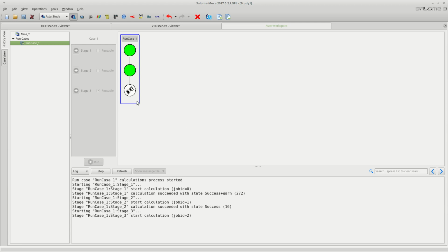Now this third stage will take a significant amount of time. The reason being, it has to save all the time steps, and the output file is also going to be bigger than what we had seen earlier. So that's why in dynamic analysis, getting the whole output is not recommended, especially when we go for nonlinear analysis. Extract only the part which you require. If you need only displacements, then only extract that part, don't extract the whole model.